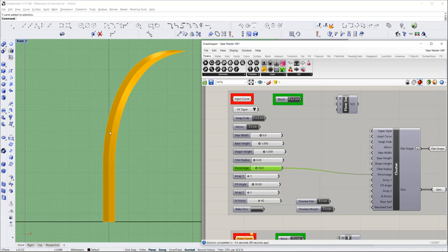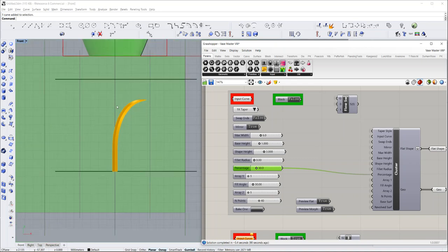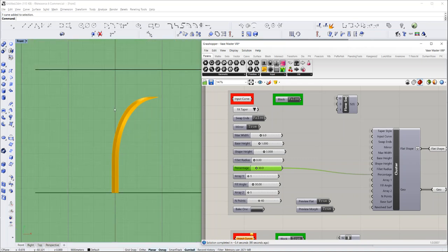So now the taper size is constant through this area, or the piece size is constant. This can be very handy if you want to add elements in here, which I'm going to do in just a second. I'm going to leave it at that 30% because I'm going to create an element that comes right up through here, and I want it to match perfectly in here. If I allow it at 100, it will create a step there because one will start slightly bigger than the other one was at that point.